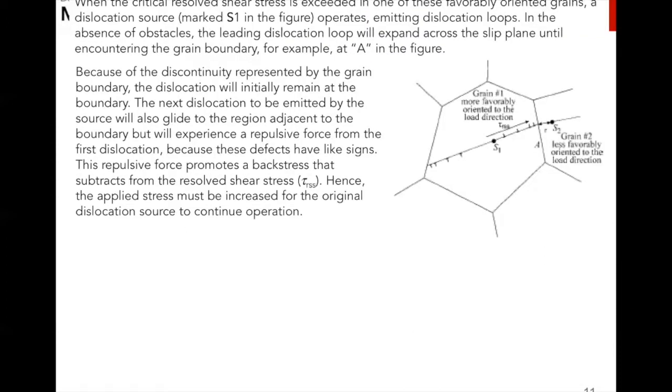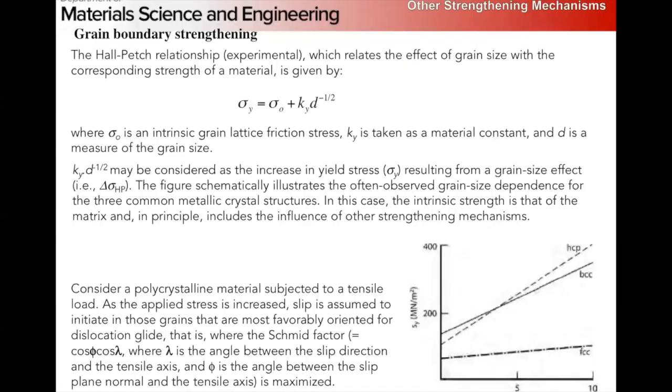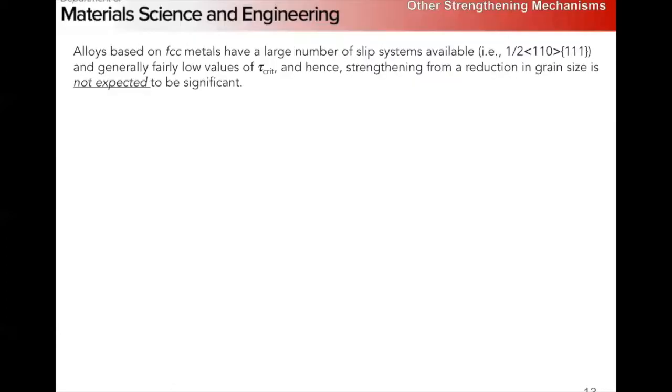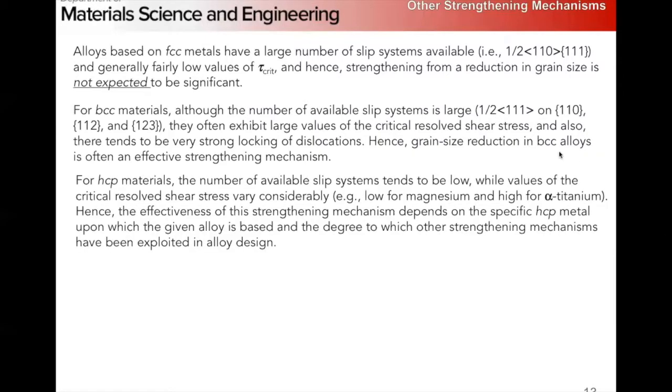Right? So basically the answer is in the slip systems, right? What are the slip systems for FCC, right? They are the 111 planes along the 110 direction, right? So we've got 12 slip systems, 12 degenerate slip systems. They all are equivalent. They have the same energy. And they tend to be fairly easy to activate, right? Remember, we're slipping on a close packed plane along a close packed direction.